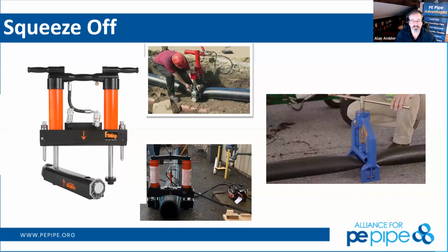Very, very robust. And when we talk about these larger diameter pipes and a hydraulic unit, it's interesting in the rehabilitation stage, if we're rehabbing an existing pipeline, as you're moving through that, either through a pipe bursting job, or if you're open cutting and replacing it, yeah, you have to control the valves to make sure that the water flow goes through there.